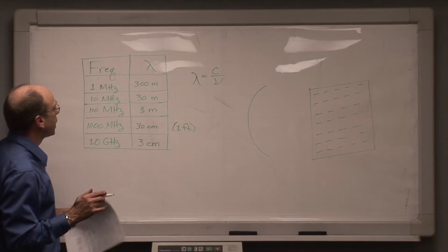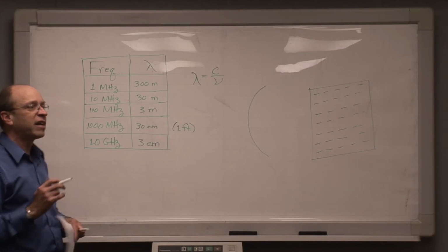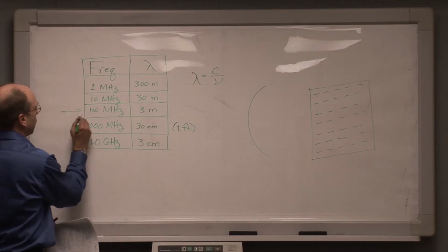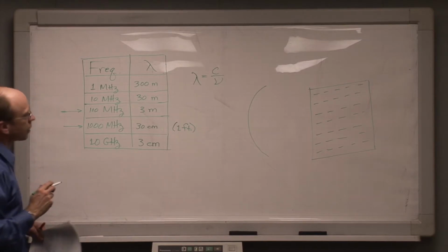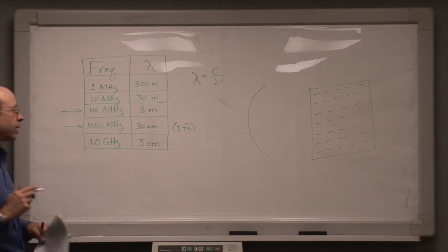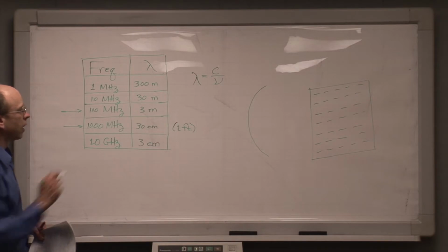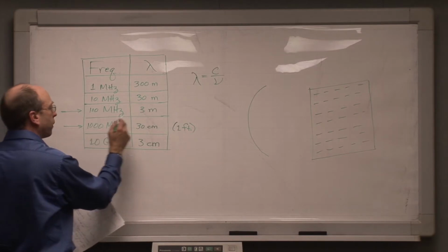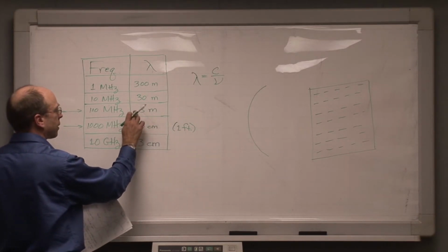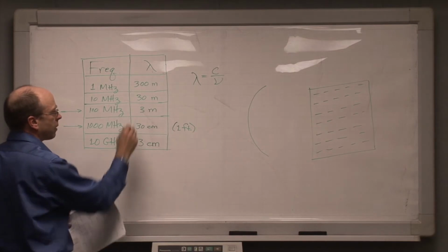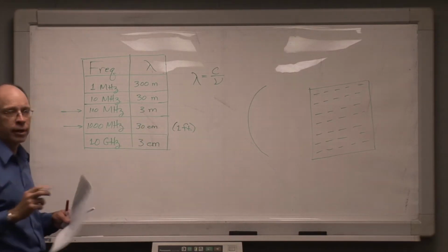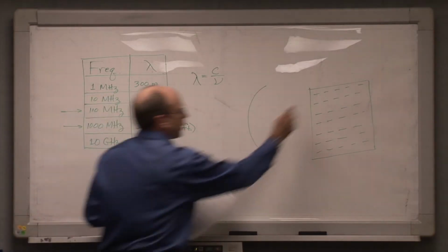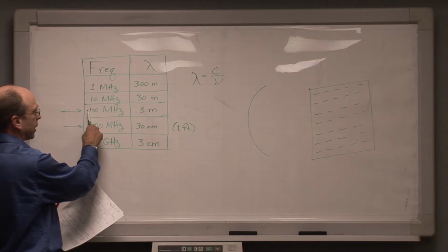So, suppose that we want to build a space search radar like PAVE PAWS. We decide that 400 megahertz frequency, which is between here and here, is a good frequency to use in terms of propagating through the Earth's atmosphere and interacting with objects in space. But we need the big antenna that we're going to build at 400 megahertz to be substantially larger than a wavelength. Well, that means that it's going to have to be substantially larger than at least a few meters. And in fact, we know that the PAVE PAWS radar, we've seen photographs of it earlier in the series, is a building that's 10 stories tall. Basically, it has to be a large building because it's working at a relatively low frequency.